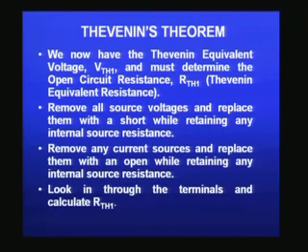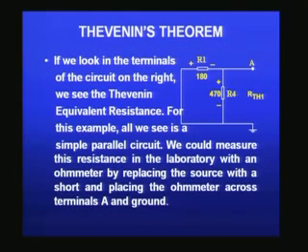Now, we have to find out what is the Thevenin's equivalent resistance, R Thevenin RTH1 for the left side. For that, we remove the voltage source, replace it with a short, and measure what is the resistance. So, you can see in the circuit shown, I have removed the voltage source and connected a simple wire, and I just have only two resistors, and these two resistors are in parallel, and therefore R Thevenin is nothing but the parallel combination of R1 and R4.